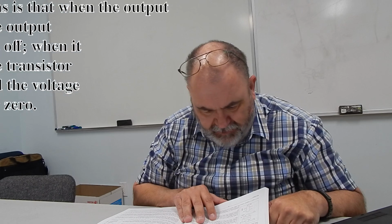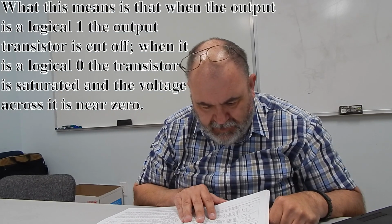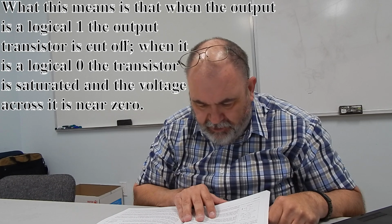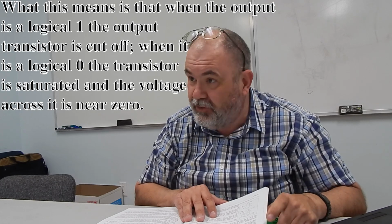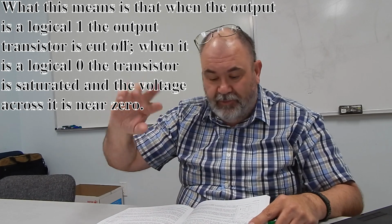Because one of the questions is, how is the output achieved in a multi-vibrator circuit? And the answer is, one transistor is turned on and the other is turned off. Oh my God, yes. Under flip-flops there on page 5.8, in the second paragraph, it says, what this means is that when output is a logical 1, the output transistor is cut off. When the logic is 0, the transistor is saturated and the voltage across it is near 0. So they actually tell you in there about this transistor thing.